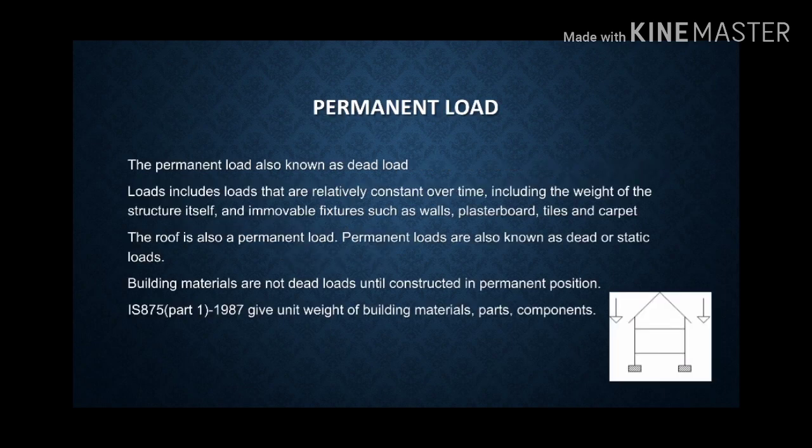Okay, now let us look at what is meant by permanent load. Permanent load includes loads that are relatively constant over time, such as the weight of the structure itself, or self-weight of structures, and immovable fixtures such as walls, plasterboard, shielding, tiles, and so on.